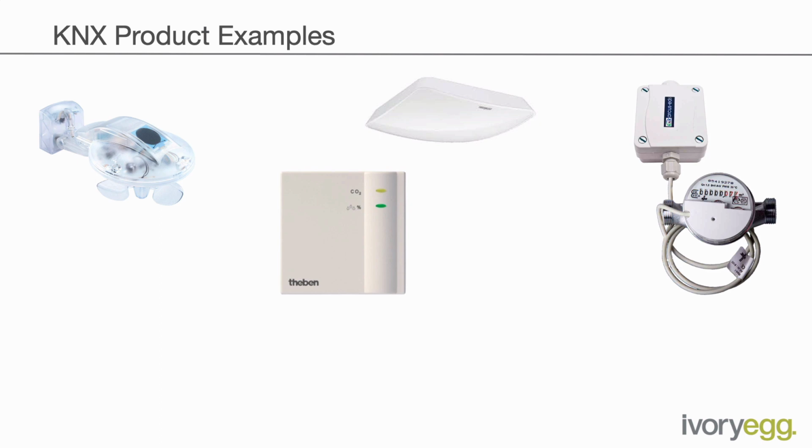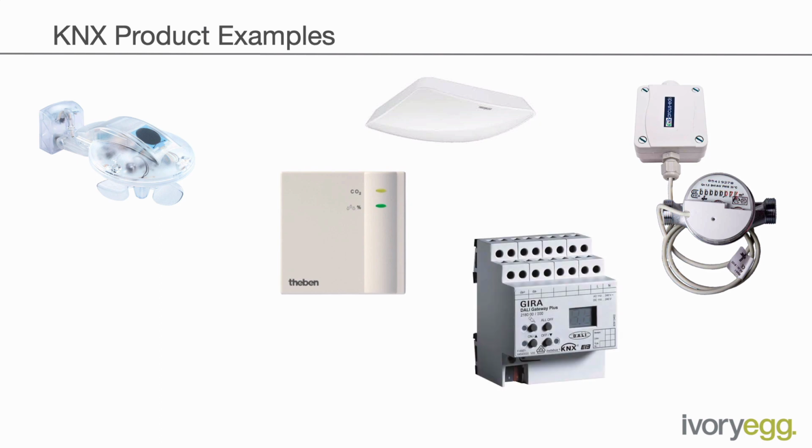So KNX provides a really good solution to that because it's already offering control of all the different parts of the building. Integrating to other systems like DALI, using DALI for your lighting control, which provides real feedback on the status of different fittings, doing things like color temperature control, or working with emergency ballast so you can automate the testing of emergency lighting in commercial buildings. Really simple with DALI, and KNX provides a great backbone to integrate that into the rest of the building.